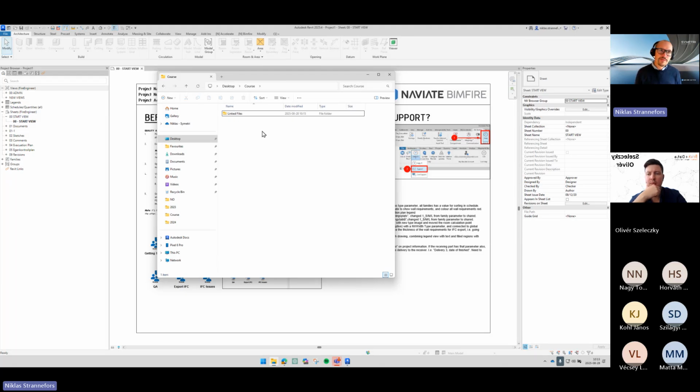So we're never going to have a naming convention on the files. I know a lot of people do that, especially working with PDF, that you have the PDF name and then a date, and then you relink every time. Don't do it. Have the same name, replace. It's going to automatically update here in Revit or in AutoCAD as well. So I'm going to emulate this by doing this. This is just a suggestion. This is how a lot of people do it, having here our linked files, here our backups, and here I'm going to put mine.